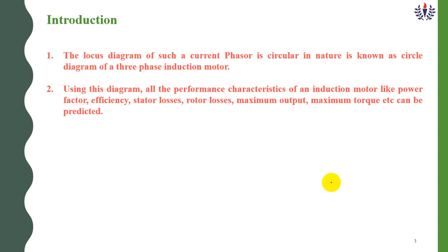By using this circle diagram, all the performance characteristics of an induction motor like power factor cos phi, efficiency, stator loss, rotor loss, maximum output, maximum torque, etc., can be predicted.